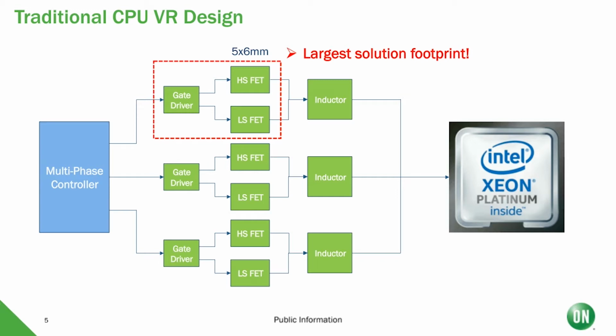The goal of this topology is to be able to do a step down in voltage that typically is going from 12 volt down to the CPU voltage, which has been changing in different generations. The core voltage has been sitting at about one volt and below, depending on the power state of the system. So if the system wants to use a lot of power to process network traffic, they will boost the core voltage to about 1 volt. But if it's not seeing much traffic, it may throttle down and reduce the core voltage to say 0.8 volt or even 0.6 volt.